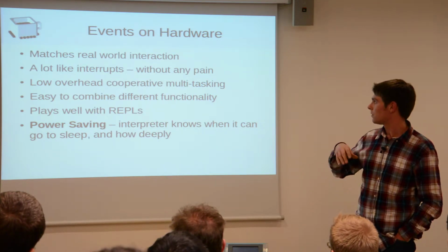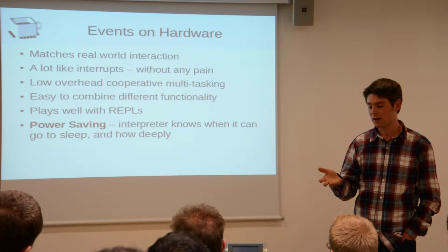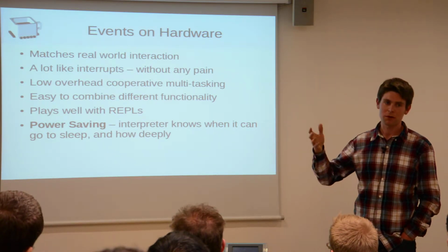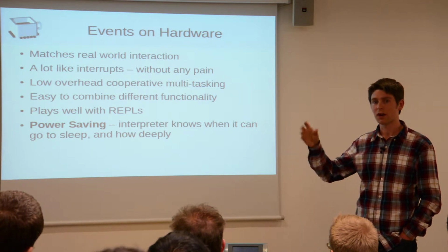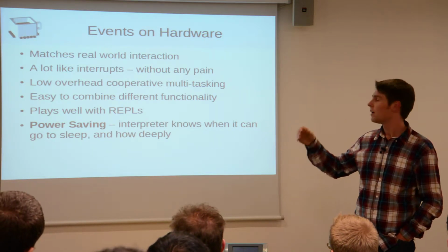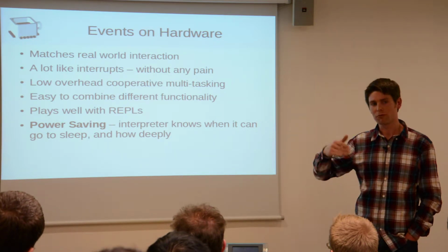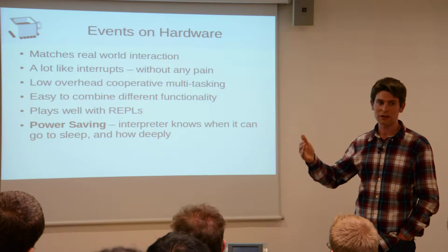And the way Espruino is implemented, at least, you set a watch on a pin like a button or an input, an interrupt actually handles it and timestamps it to the nearest microsecond, and then it goes back and handles the JavaScript in the event loop. So even though it's not running it instantly, you can still do things quite accurately.